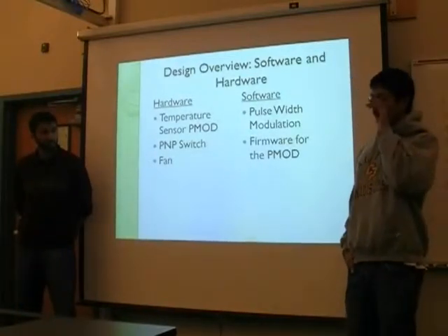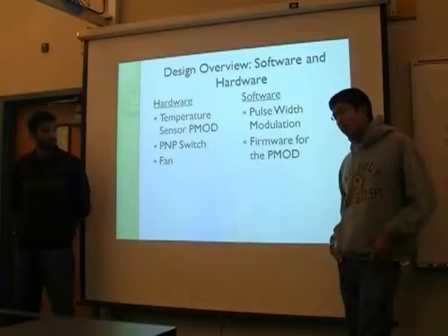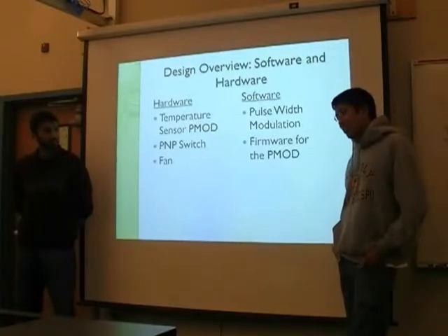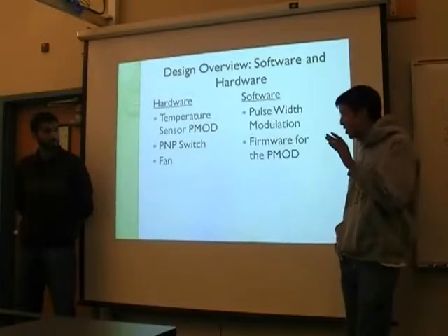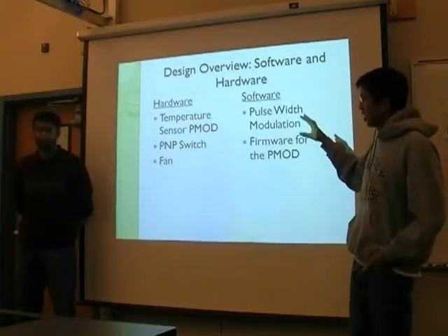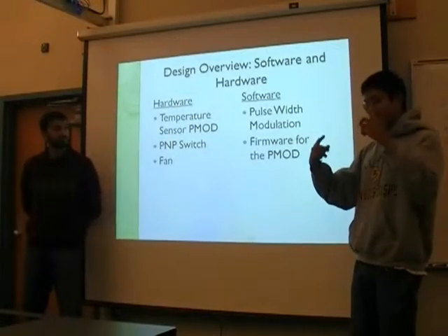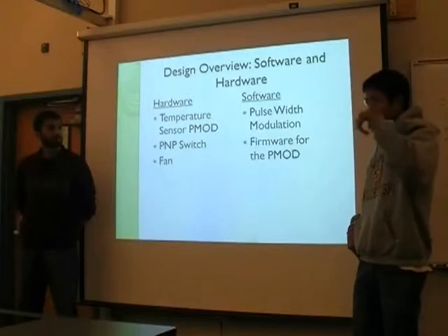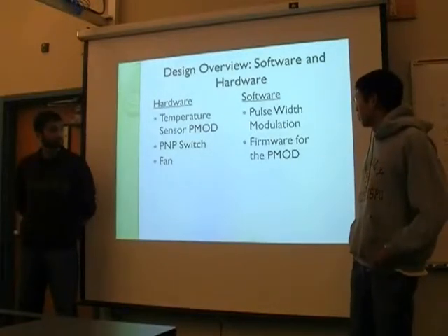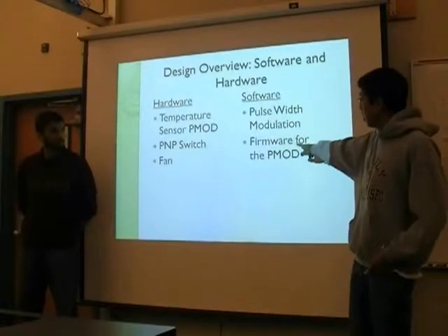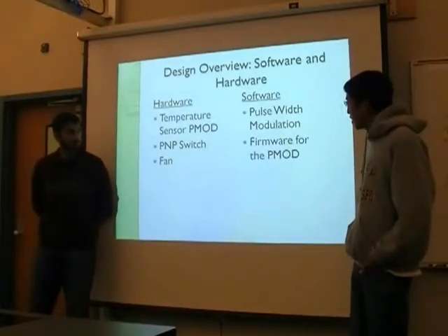Our first approach was to use the function generator from experiment 4, but that fell through because we used the interrupt, and it did funny things when the interrupt was running while the temperature was also converting. So we just made it use the timer counter, and then we wrote the interface for the temperature sensor.